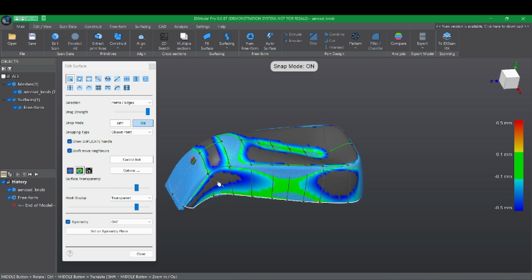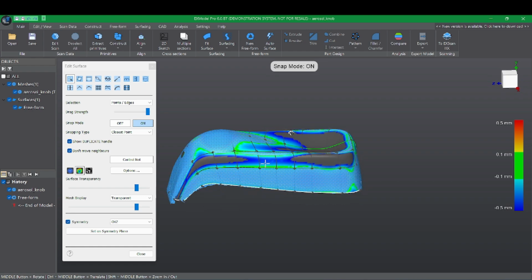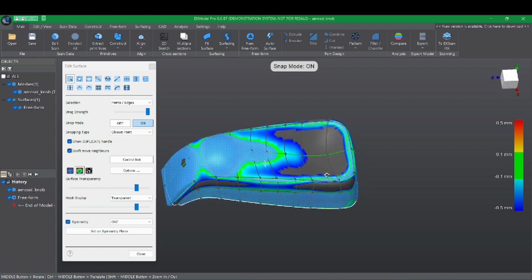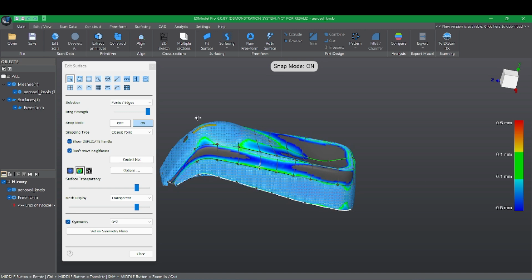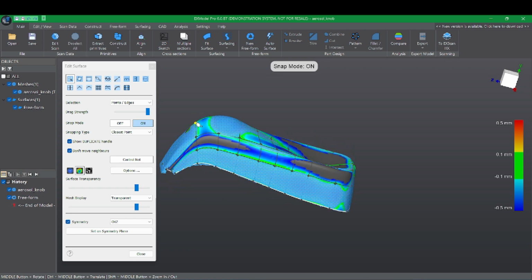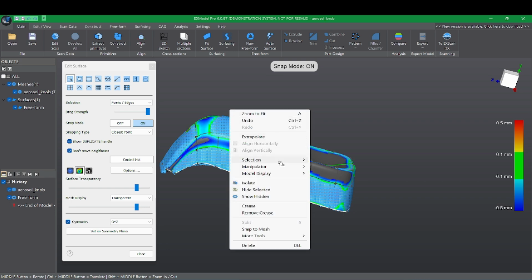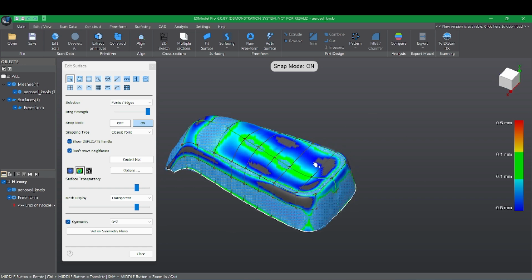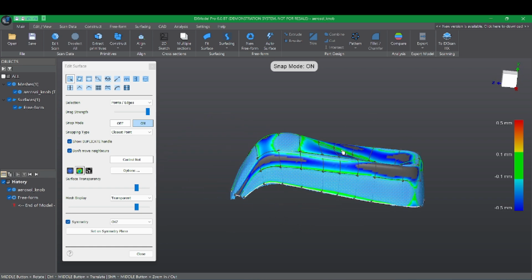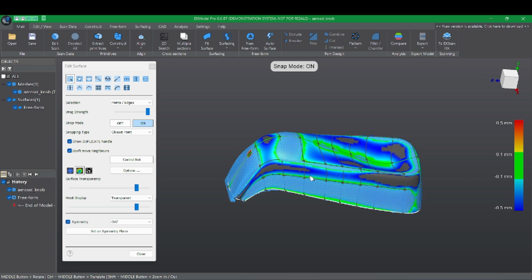During the modeling, the software always tries to keep the points on the surface, but if you combine this, for example, you switch this off and you move, now it floats in space. It's not at all on the mesh. You can turn this on, and at any point you can just right click and tell the software to snap all the points on the mesh.